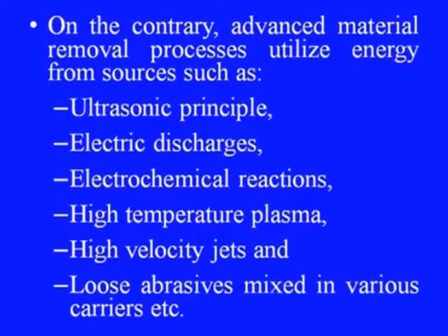The advanced material removal processes utilize energy from sources like the ultrasonic principle, electric discharges, electrochemical reactions, high temperature plasma, high velocity jets, loose abrasives mixed in various carriers, and other electromagnetic energies, etc. Originally, these processes were developed to handle unique problems in the aerospace industry for machining very hard and tough alloys.